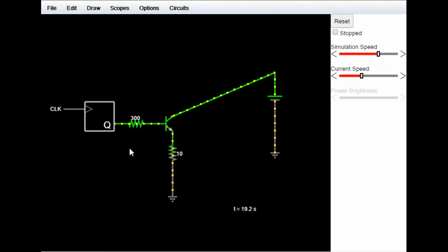Well, for one, we added an extra bit of resistance to the microcontroller. So now the microcontroller not only has to drive this 300 ohm resistor, but the current has to come down here and go through this 10 ohm resistor. And in fact, this is going to be a variable 10 ohm because it's a motor, so it's a little unpredictable there. But that doesn't really add up. If you do the math, you have 310 ohms and 5 volts, and the current should be a lot higher. And if I highlight over here, you can see that it's 3.2 milliamps going through this resistor. So something else kind of weird is going on here.